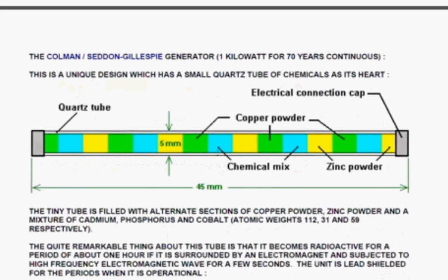3 kilowatts is substantial. Your biggest load typically in a house is a washing machine, which at times can take 2.2 kilowatts. Usually it takes a good deal less. Alternatively, a tumble dryer can take about 2 kilowatts, typically, and they're effective. So you can run a washing machine and or a tumble dryer, which is one of the biggest loads you get in a house. Most of the other things are very small by comparison.